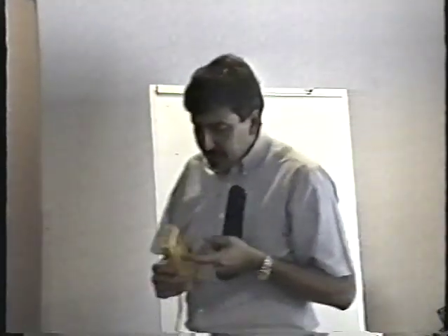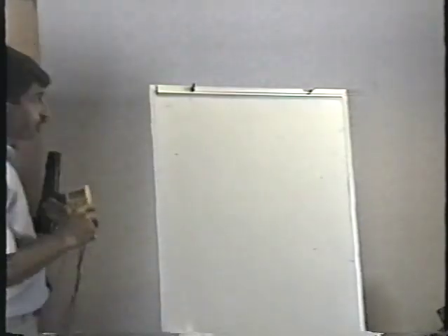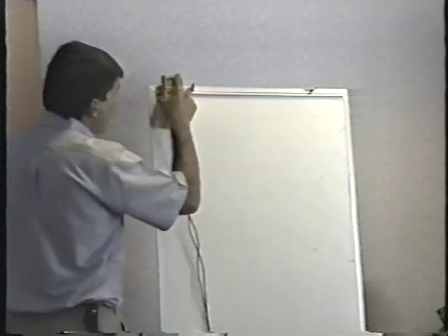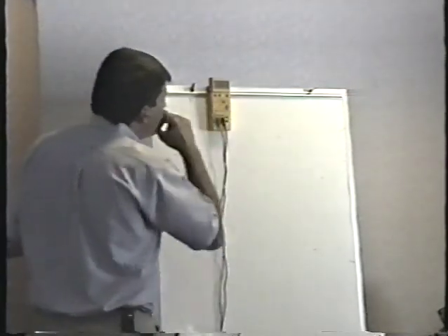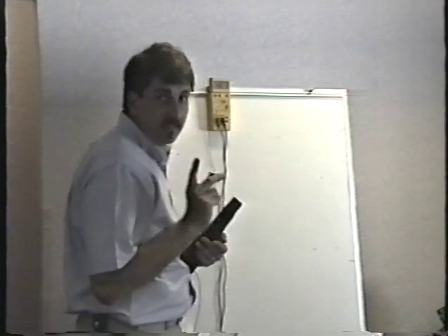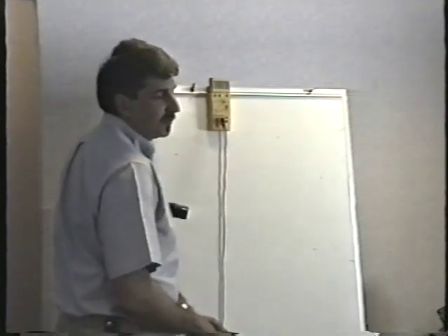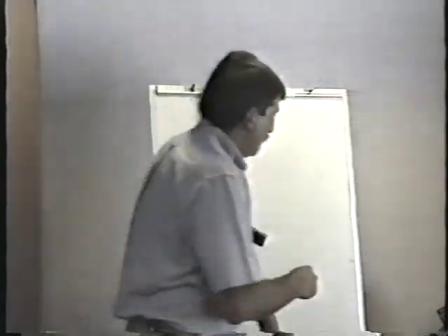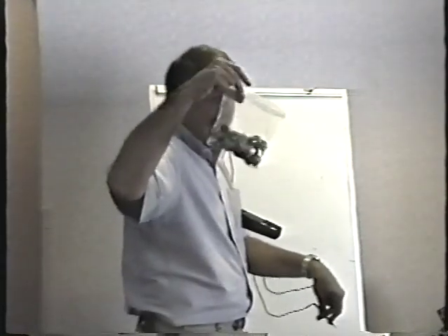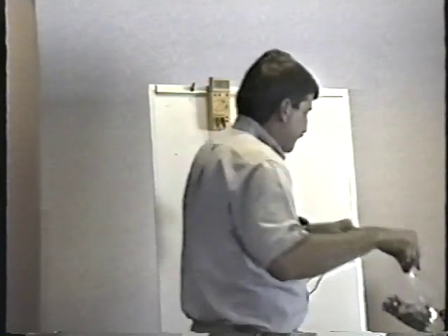And if you look at the chart on the top of page 10, this tells you how the transistor test works. And again, you're using the diode test setting of your meter. Using the diode test setting. Here's how this works. Don't do it now, just watch me. You're going to have a chance to do 40 transistors in just a few minutes, okay? Because I got this big bag of transistors here. You're going to check every one of these. Half of them are good, half of them are bad, and you'll see how this works.